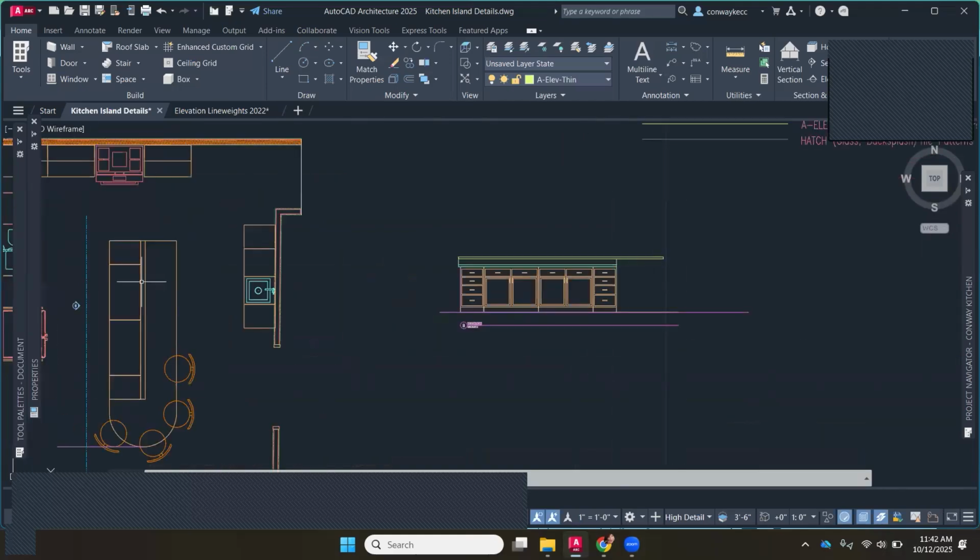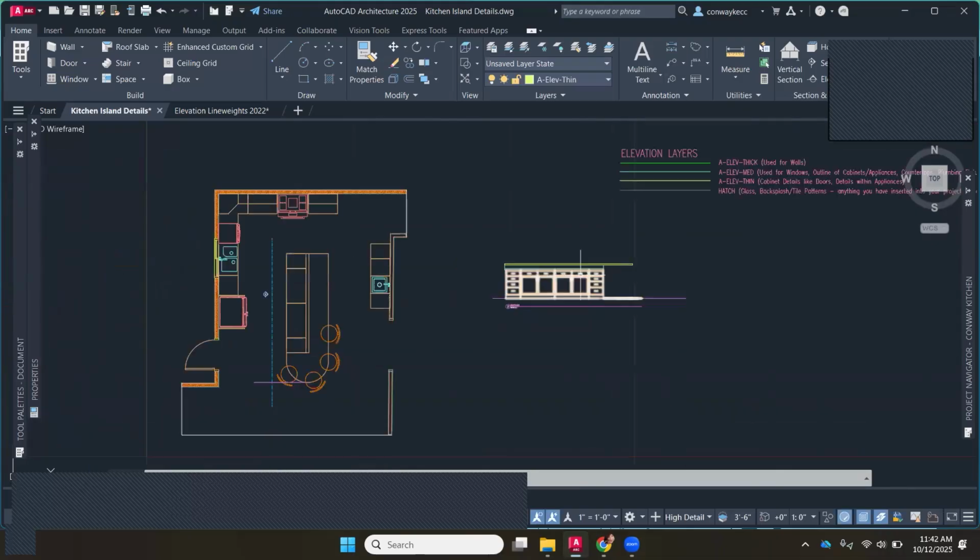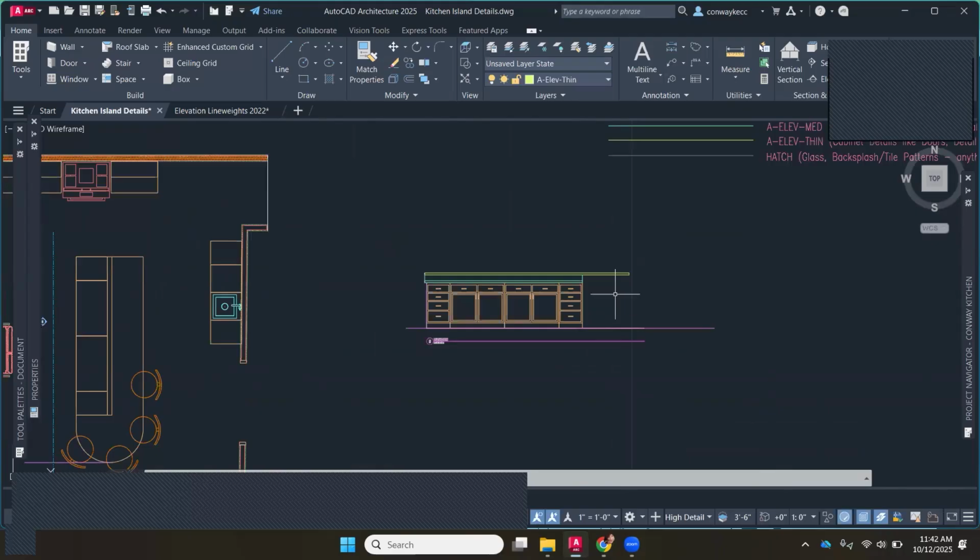Now, I have a wall running most of this way supporting this. This is where you're going to talk to the fabricator and ask, is that enough? No, it's probably not. There's probably going to be a lot of brackets here. There might even be a leg here. So in my case, I might need an elevation looking this way, showing all the little brackets. But for now, what we're doing this semester in class, that works okay.